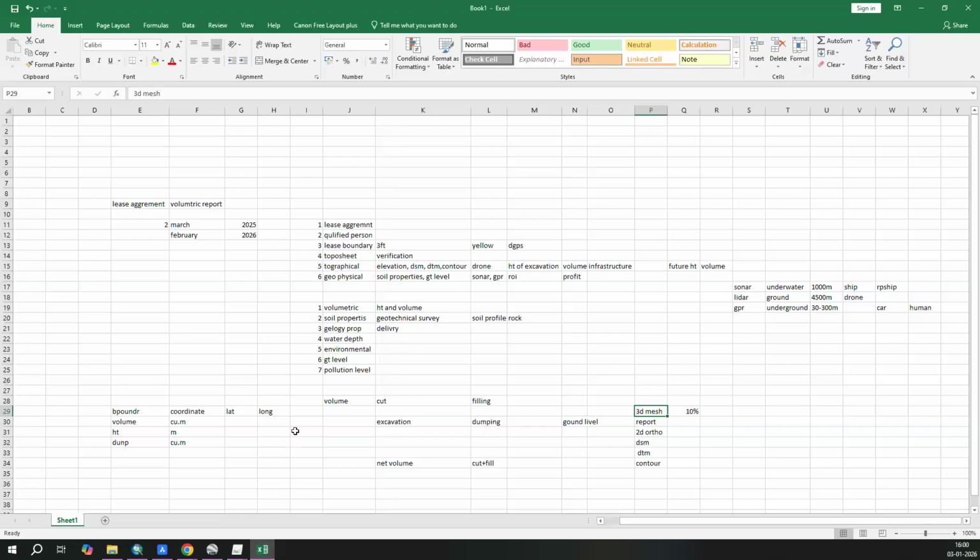This is not like your regular 2D survey, where it is only mandatory to have at least 5 points per square kilometer. Here, you can even have 10 points for one particular mining site. The more points you have, the better accuracy you have. Whereas in your 2D survey, since there will not be so much volume or elevation issues, you will follow the minimum of 5 points.